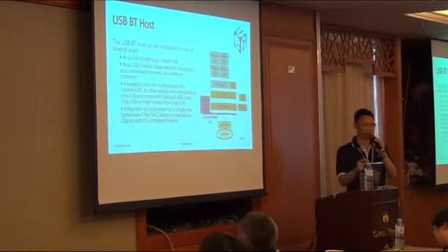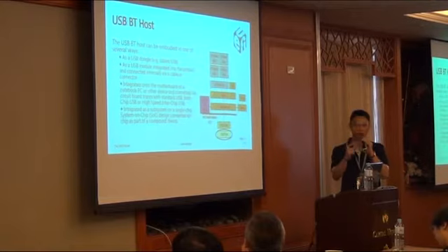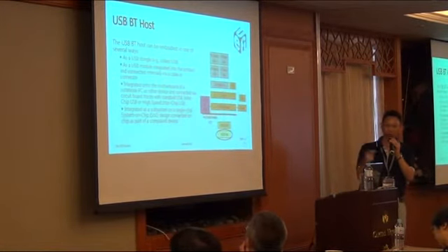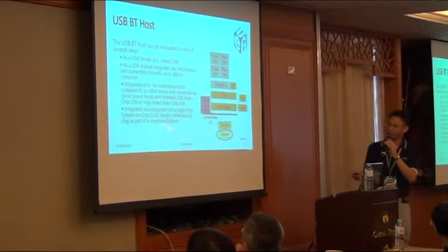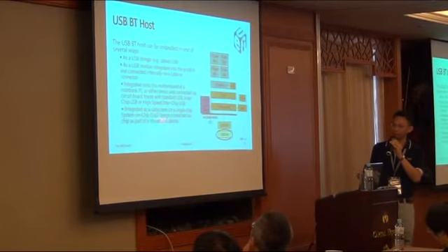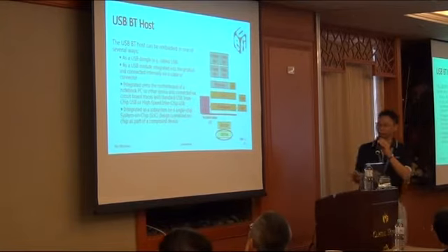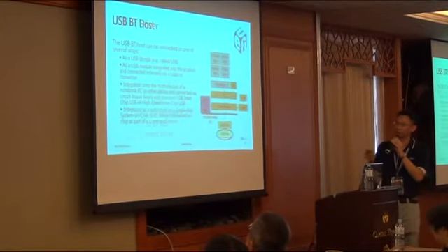Right now there are many modules with a PCI Express connector available in the market, combining Wi-Fi and Bluetooth. So if the system has a PCI Express connector, you can use it to get Bluetooth. It can also be solely connected to your platform, or added to an SoC chip. Those are the ways you can have support for the Bluetooth host.